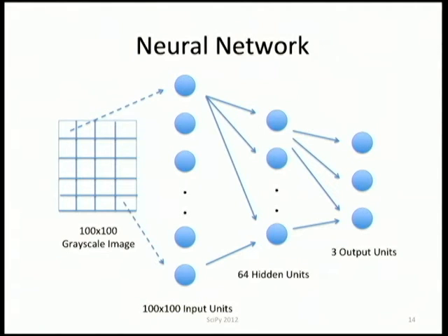The way this thing works is first of all, it's a multi-class classification neural network. And it's not predicting one thing, it's predicting 3 things. So at the very right-hand side, you can see 3 output units in this neural network. These things correspond to the 3 actions that the robot takes. It can move forward, it can move left, or it can move right. So the idea is that looking at the image on the left-hand side, or rather looking at a vector of the grayscale values of the image, which goes into the input layer, the first layer of the neural network, what should be the output?